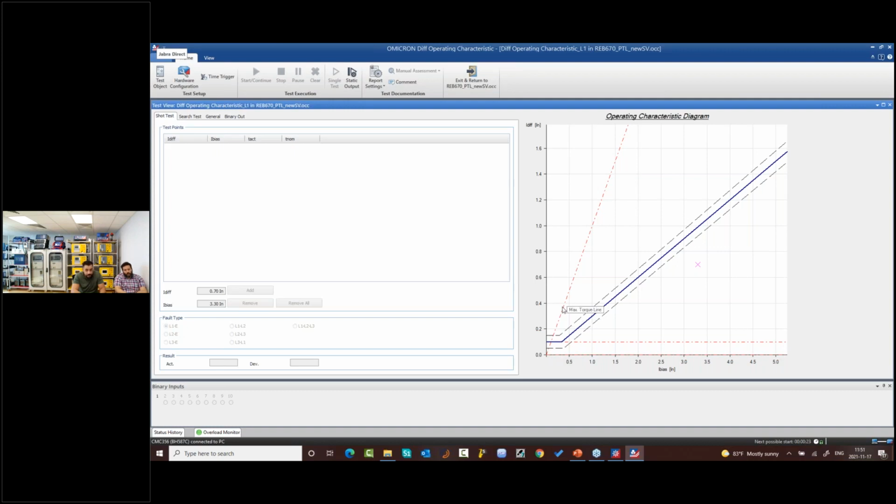But some of the people will say it doesn't look like 45 degrees, it looks like 60 or 70. We will say that you can look here, and you will see that the scale of the x-axis is different from the scale of the y-axis. So if you calculate any x and any value of y, you will see it is here 0.5, and it is here also almost 0.5, so it's 45 degrees. Here is the blocking characteristic region, the blocking area, and here you can simulate any fault because it is not applicable in the power system.